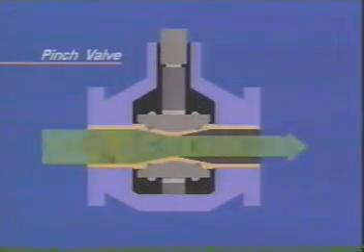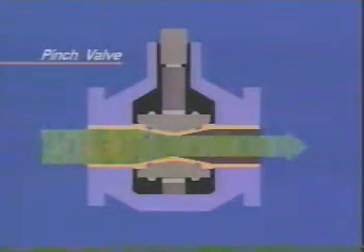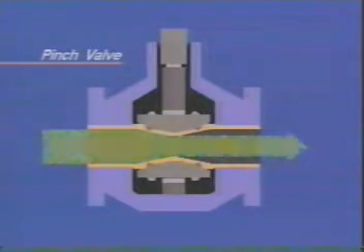Throttling is provided by squeezing and distorting a hose or tube. Notice in this valve that the actuator is attached to the tube wall. This construction allows the valve to operate in a vacuum service. Other designs rely on process pressure to reopen the tube.